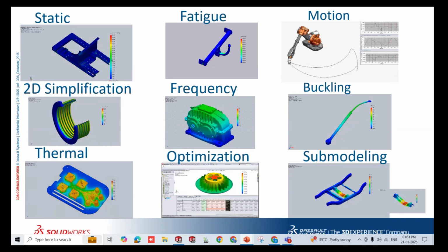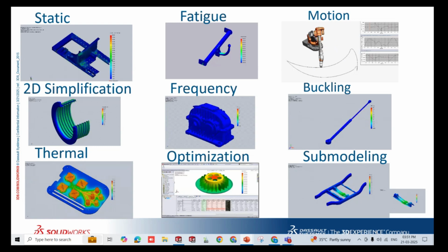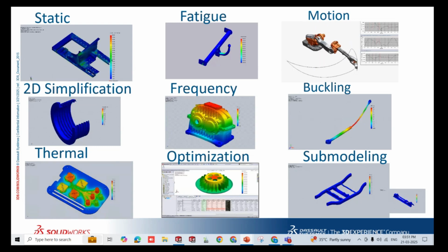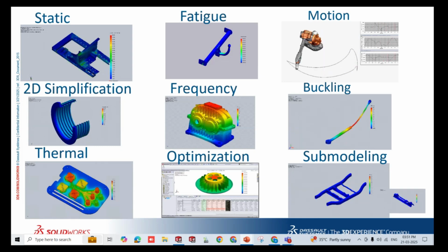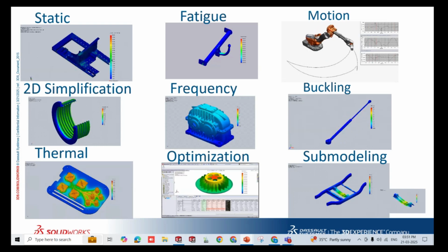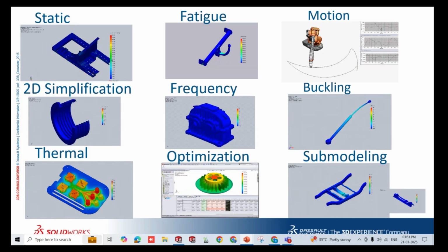Sometimes, especially in high-tech industries, you have epoxy or glue in between parts, right? These are typically very thin, so you do not want to model them and mesh them. What we can do is use this thermal contact resistance and just model the effect instead of directly modeling the epoxy resin, which is a thin layer. That is where thermal resistance comes into play.